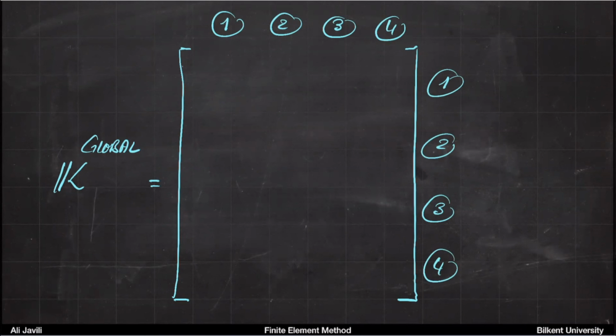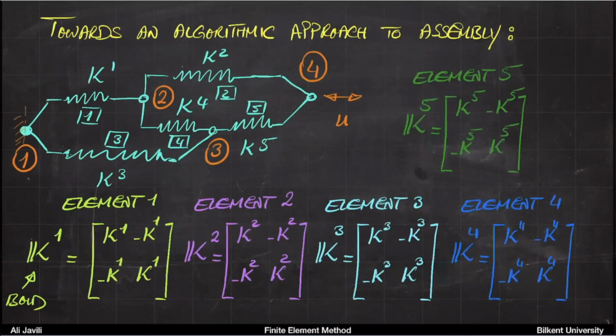But then, as we spoke previously, if you think of a node 2, here you would have a stiffness 2,2. You can't expect that node 2 is only here. You can expect that at node 2, you would have contributions from element 2, from element 4, from element 1. And using what we did today, I mean, we are going to number this shortly, this is going to be a very simple process for us.